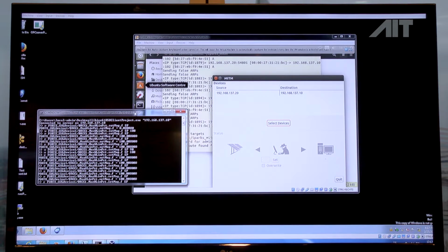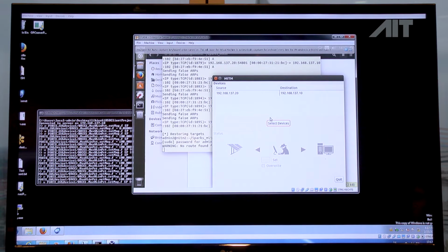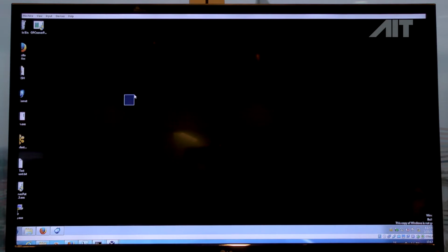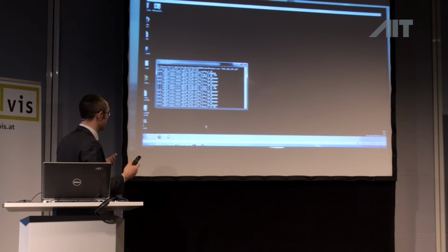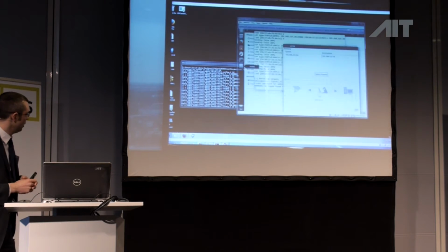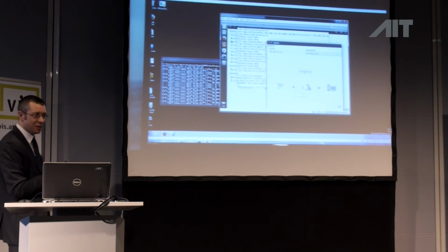It's difficult to see at the back, but we can see that it's operating at 100% power. So now the system administrator, the grid operator, from his distribution management system, this IEC 61850 client, sends a message to the PV inverter to reduce its active power output to 80%. So it might do this, for example, because of... why would they do this? I don't know. But they would do it anyway.